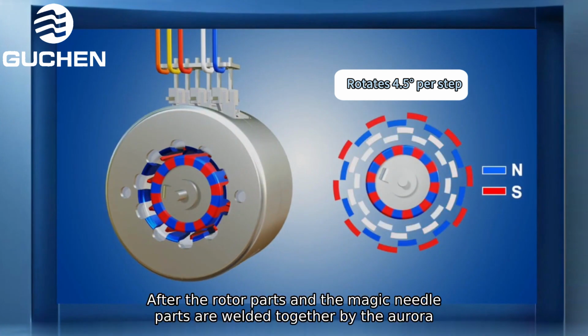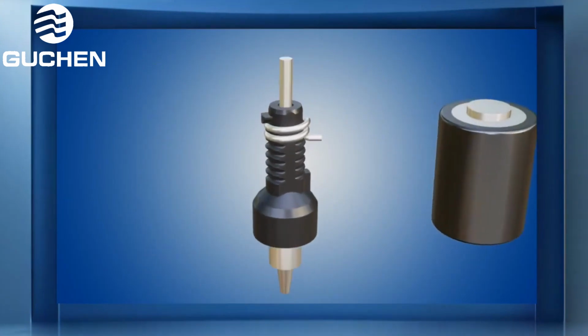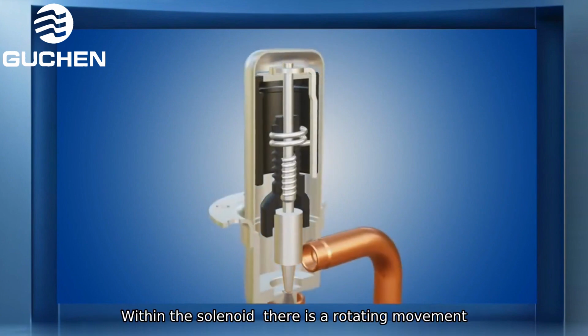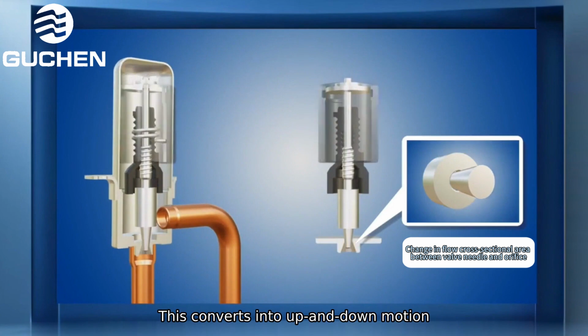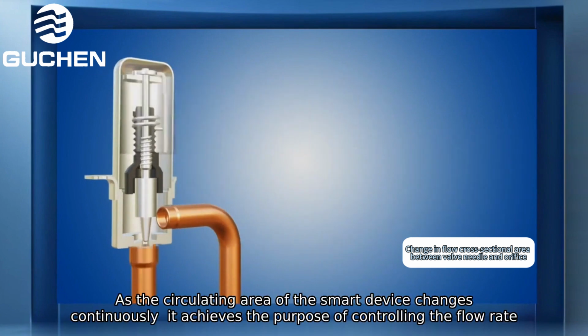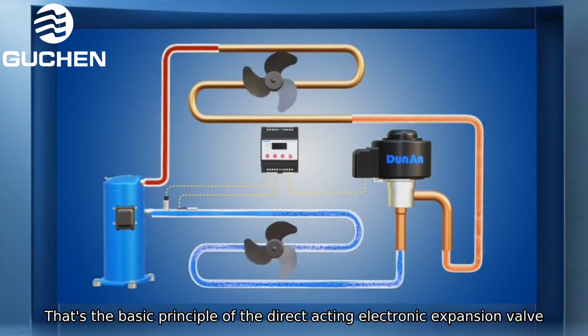After the rotor parts and the valve pin parts are welded together, the winding drives the rotor by generating a magnetic field within the solenoid, producing a rotating movement. This converts into up and down motion. As the circulating area of the refrigerant changes continuously, it achieves the purpose of controlling the flow rate. That's the basic principle of the direct-acting electronic expansion valve.